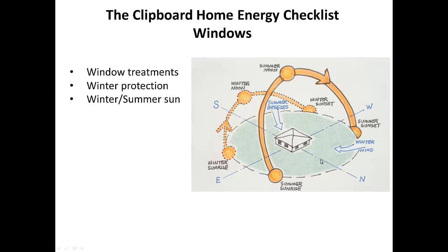So in the summertime then, the windows that are particularly vulnerable are the eastern windows here where the sun is beginning to climb, and now we're in the heat of the day. The air conditioning is working hard, and if I've got a bank of windows on the west side of my house over here, this summer sun is just kicking up that air conditioning and saying, work, you son of a gun, work, because I'm just pouring my energy into the home. And this is also why a passive solar home works in the wintertime, because in a well-designed home, you put the majority of glass on the south side so that this low winter sun goes right into the home.